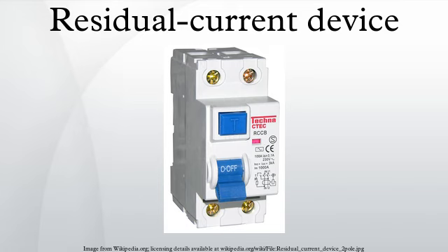False trips were frequent when insulation problems were compounded by long circuit lengths. So much current leaked along the length of the conductor's insulation that the breaker might trip with the slightest increase of current imbalance. The migration to outlet receptacle-based protection in North American installations reduced the accidental trips and provided obvious verification that wet areas were under electrical code required protection.